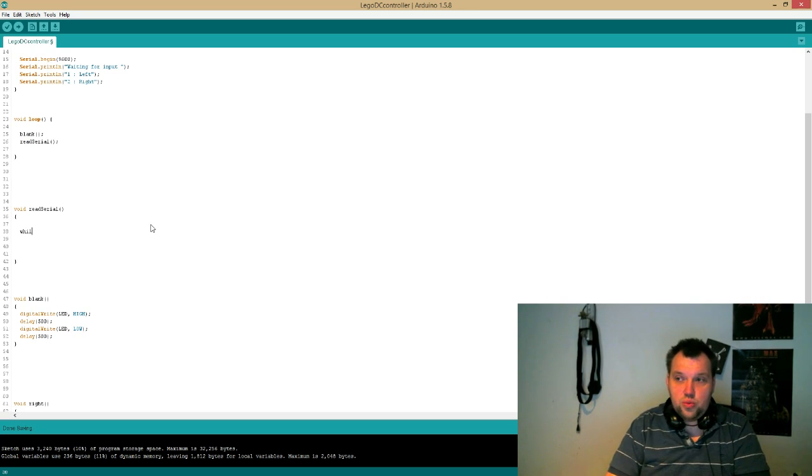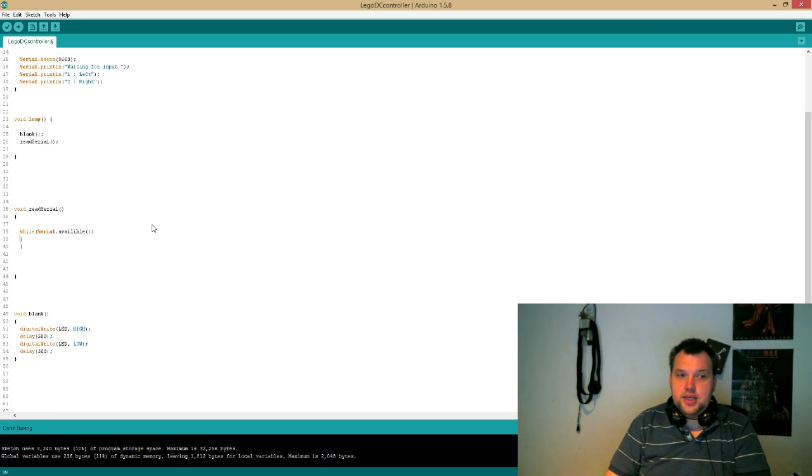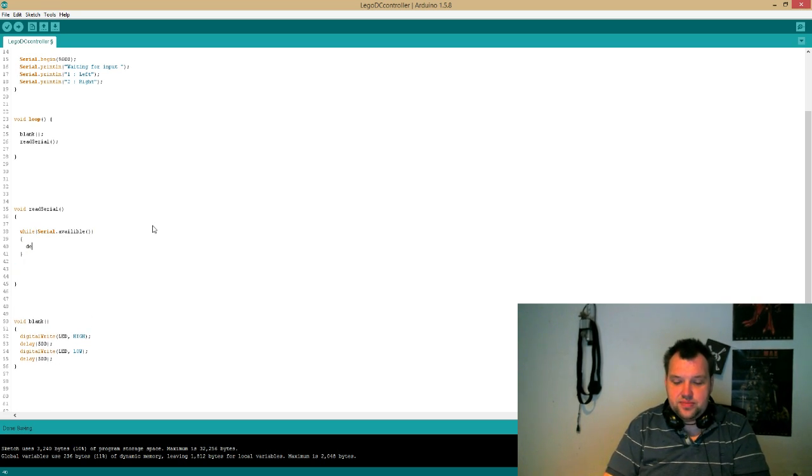So first, while serial. This one is actually going to check, is there any serial data available? Did the user input anything at all? Then the next one, I'm going to add a delay just for good measure.